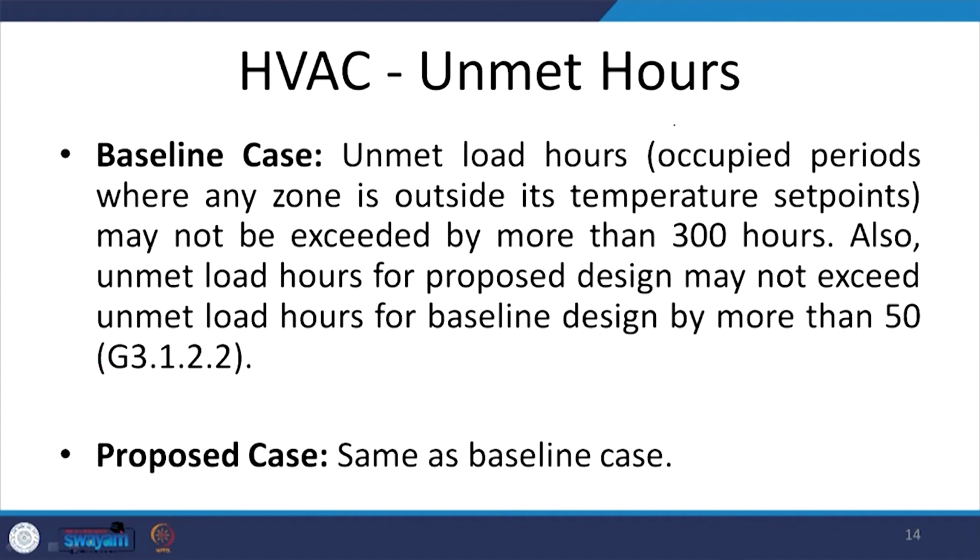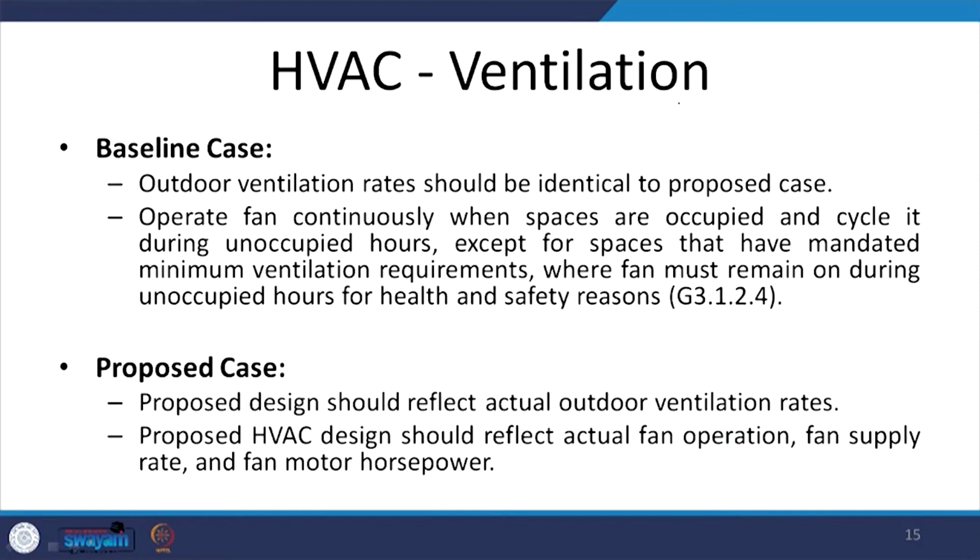In case of HVAC unmet hours, the unmet load hours for the base case will not be exceeded by more than 300 hours, and this varies for different codes and standards. However, for the proposed case, it will be kept the same as the baseline case and there will not be any variation in this. So, this remains more or less the same. In ventilation, the outdoor ventilation rates in both baseline and proposed case will be the same, reflecting the actual outdoor ventilation rate.